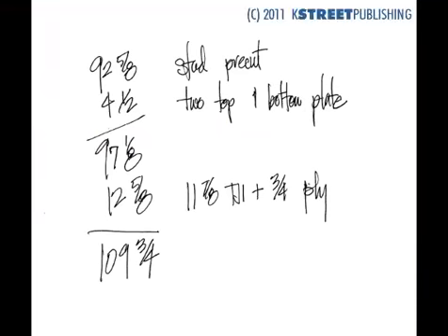So you can see here by our calculation, the height that we're working with was determined by a pre-cut stud, 2 top plates, 1 bottom plate, which gives us a height of 97 1/8 for our wall. Then the floor thickness is 12 5/8 of an inch because it's 11 7/8 inch TJI plus 3/4 inch plywood. So it gives us a total height of 109 3/4 inches.